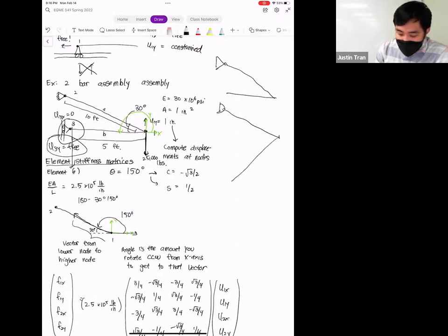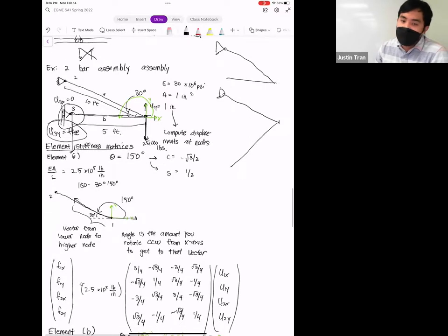And so I think for this one, it might be something like this, right? When that truss bar reaches that angle, then it's going to be stable, and then you can actually compute something. But what this is telling us is that in this configuration, where this truss bar here is horizontal with this roller, it's under constrained and it can't hold this for that much longer if that's a roller. So it's saying that this configuration is unstable. That's basically what it's saying.